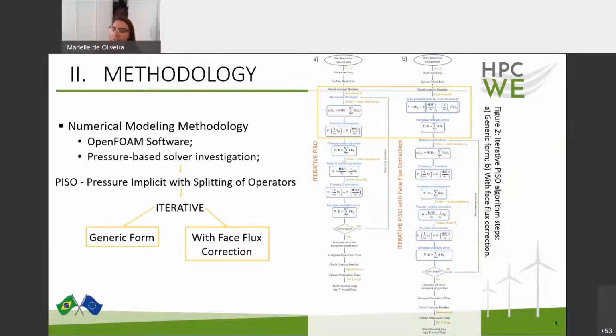The iterative approach has advantages since for each time step the algorithm solves the pressure corrections twice until reaching the desired tolerance. However, in this work, since the mesh considered in the CFD investigation is dynamic, besides the normal pressure correction, an extra correction for the flux which crosses the mesh cell's face is also considered to verify its influence on the results accuracy and computational costs as well.